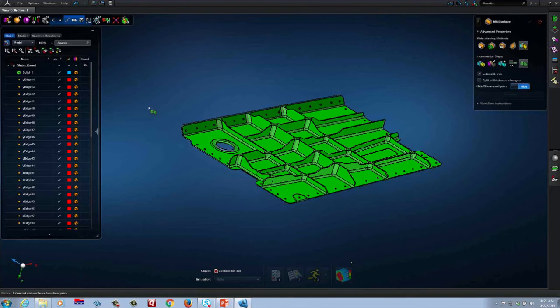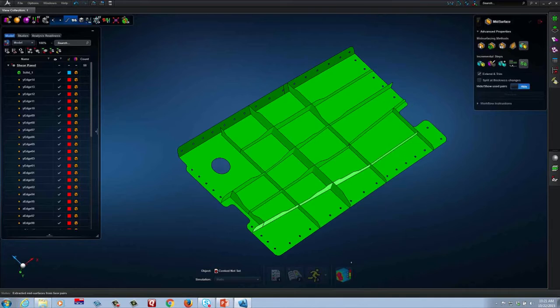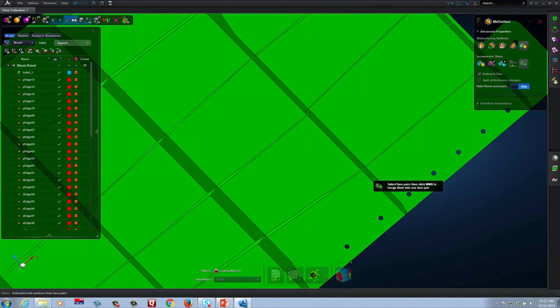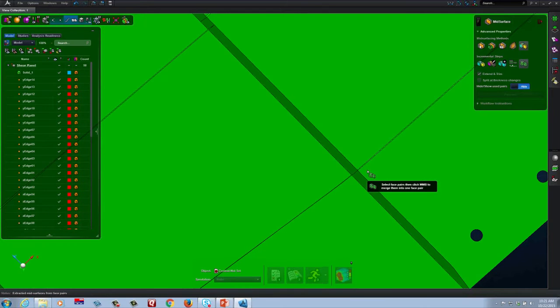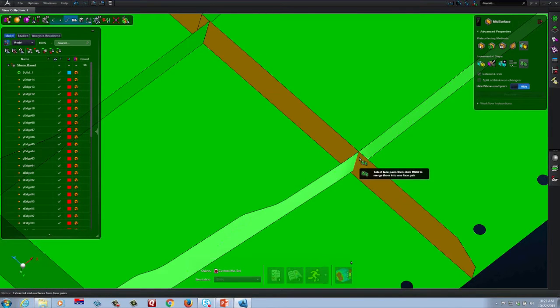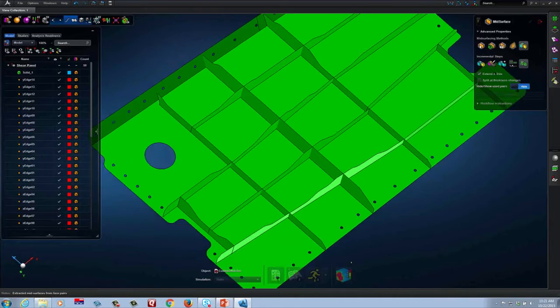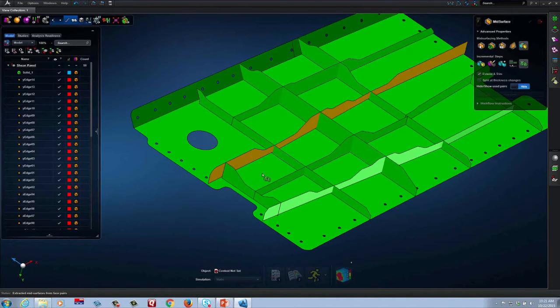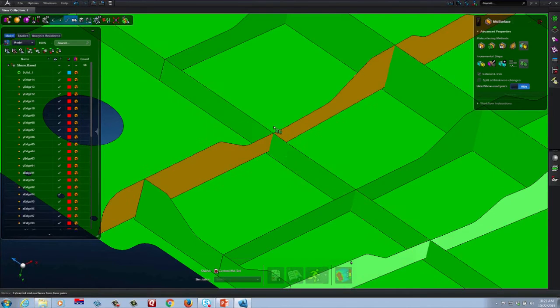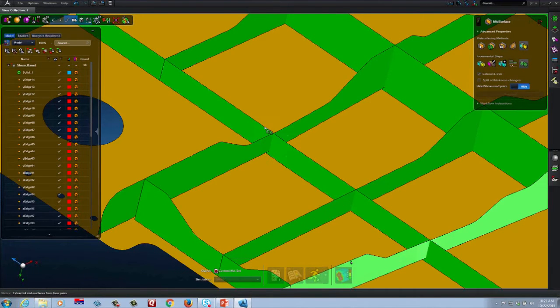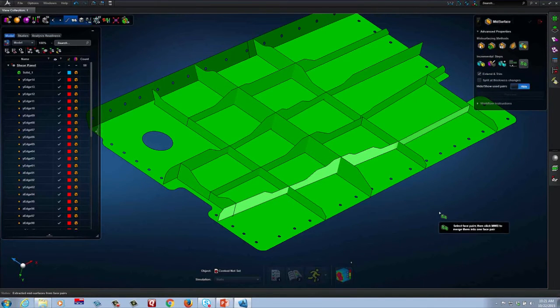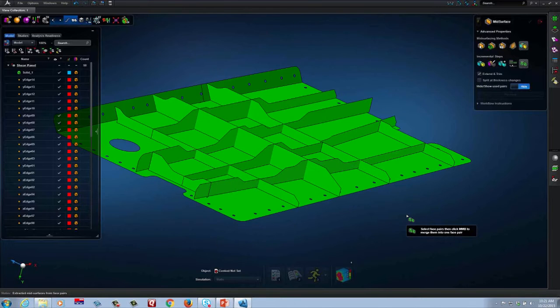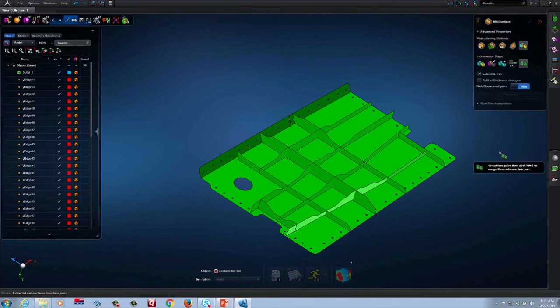And after we get our mid-surface extracted, I'm going to go ahead and hide the solid so we can look a little better. And I can see that I absolutely have captured my intent. I actually have this meeting at a common intersection there. If I look in this area here, I had some gaps. I had a really, once again, very messy looking problem here where this was supposed to intersect, and that's totally been corrected as well. So I've actually extracted mid-surfaces with just a very little bit of input from myself, and I've captured my intent once again. I've got the mid-surfaces that I want.